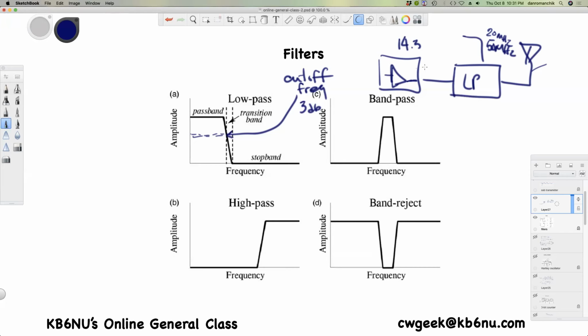So if your radio has an output impedance of 50 ohms, you want the input impedance here to be 50 ohms. And then obviously you still want the 50 ohms output here. Why is that? Well, you want everything to match so you can transfer the most amount of power. So this eats up as little power as possible, or doesn't create any kind of SWR mismatch, which would prevent the power from getting to the antenna.